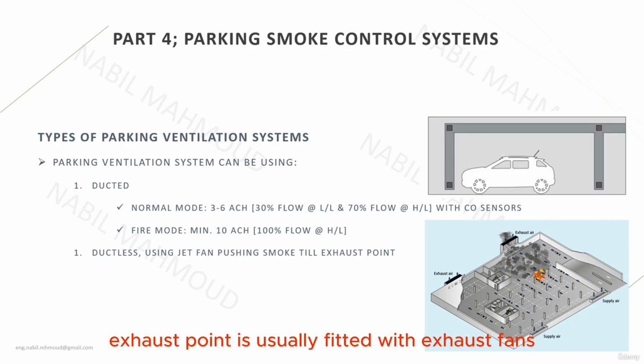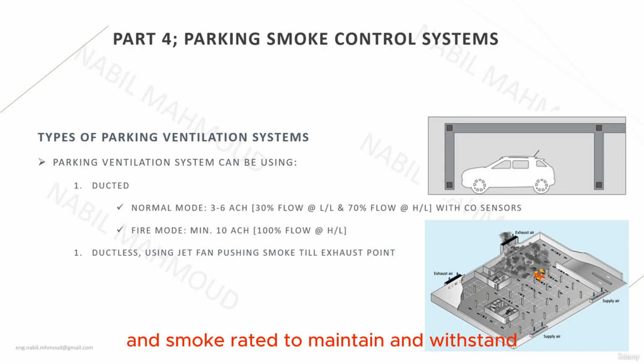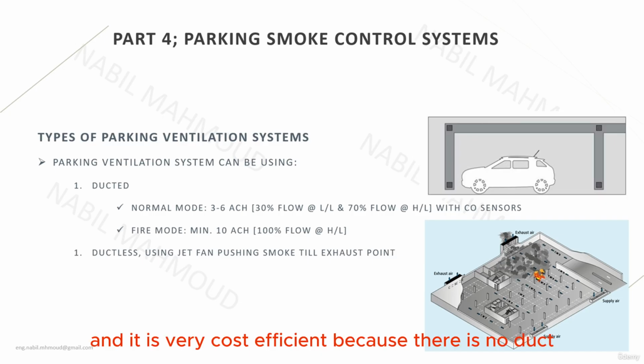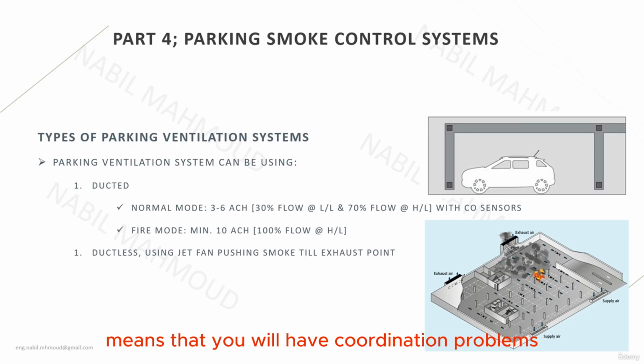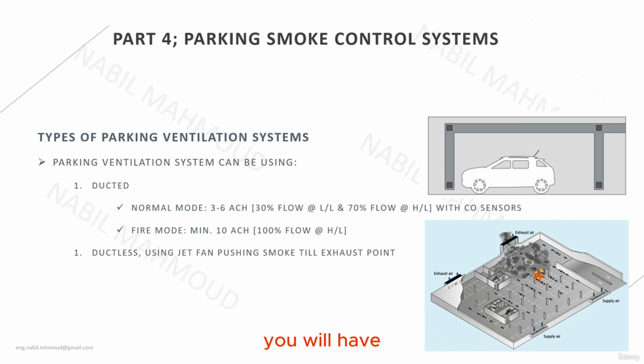The exhaust point is usually fitted with exhaust fans, and the exhaust fans are fire rated and smoke rated to maintain and withstand the hot smoke. So it's a very simple system, the ductless, and it is very cost efficient because there is no duct. And of course, having a duct running all over the place means that you will have coordination problems and coordination clashes with a lot of services in the parking.